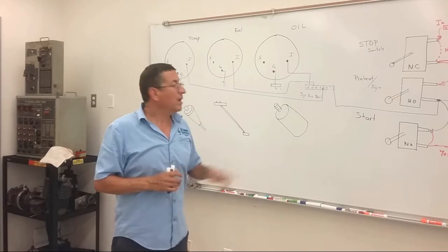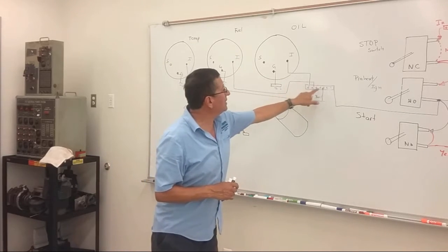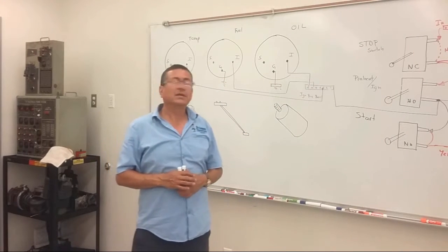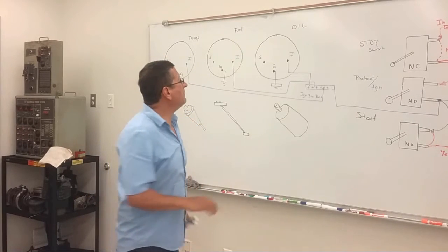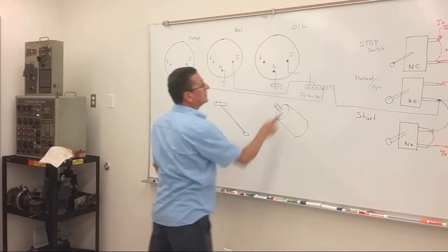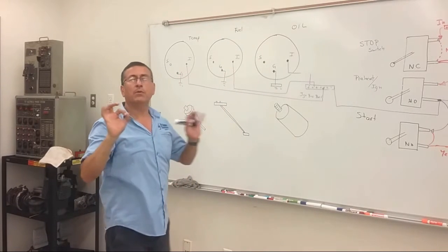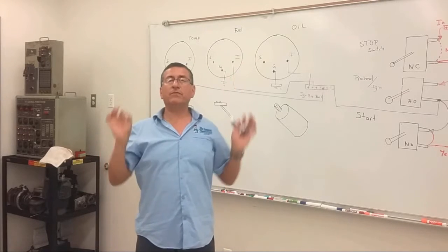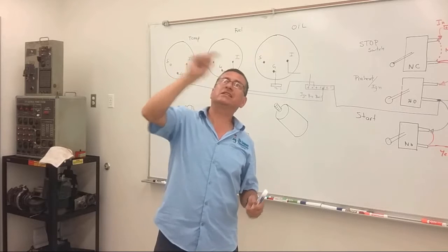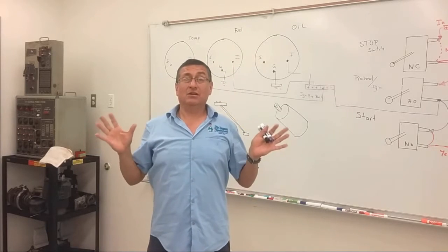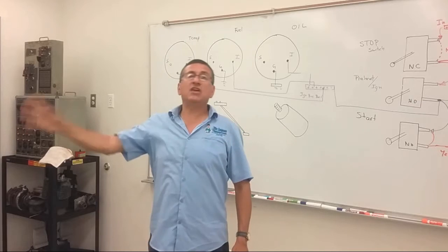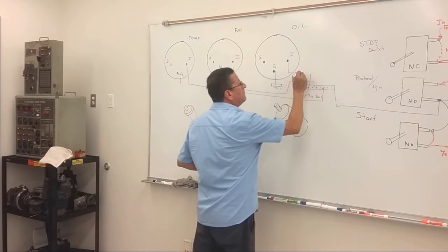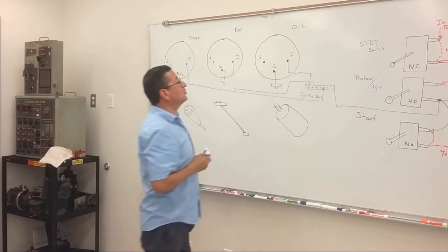In this way, what type of connection is that? I create the ignition bus bar, and each gauge is connected from it. This is a parallel connection. What happens if this one is damaged? The other ones are working properly, in parallel. Don't forget, the majority of people, 90% of the boats, if you check the console, are connected in series. For that reason, when one gauge is damaged, all the gauges are damaged. That's not good. Connect in parallel. Alright, in parallel, I am going to connect the ignition position.